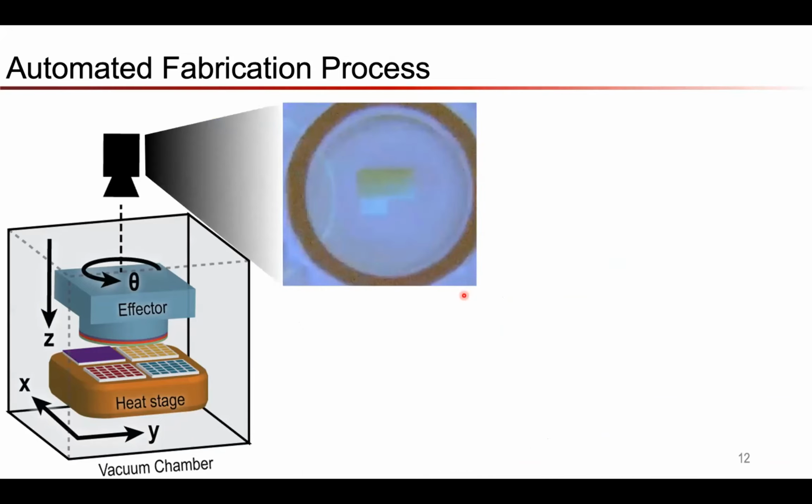This is us constructing a 16-layer heterostructure that systematically varies the thickness between 1 and 16 layers so that we can use this for optical testing for high throughput characterization. And this has actually been sped up by a factor of 100, but still this process completed in about 40 minutes to complete the 16-layer heterostructure. And in principle, it could go even faster, perhaps by a factor of 2 better than that at least.